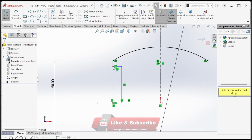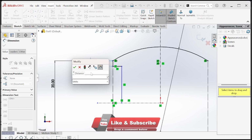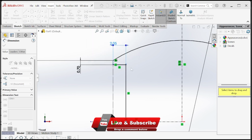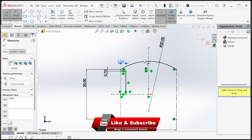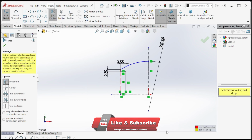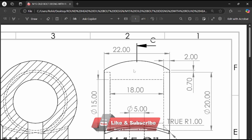So let's make this one first. Go to smart dimensions, select this point and this line and make this one 0.7. Okay, 0.7, and this one is how much? 2 mm, because it's in the drawing. Now let's trim this thing and trim this one also. No need to select anything. Now everything is done as per drawing.